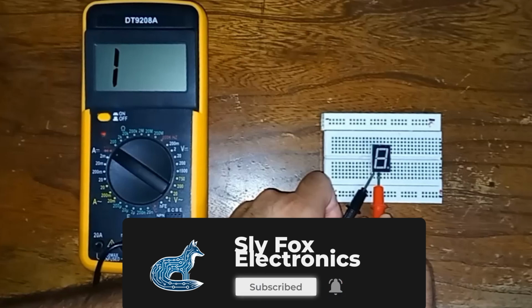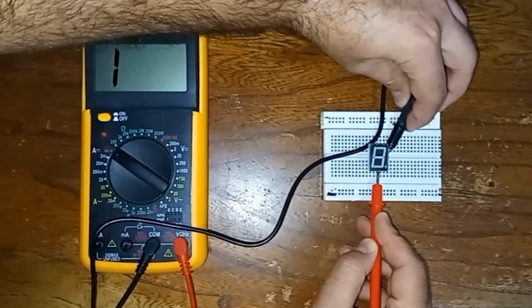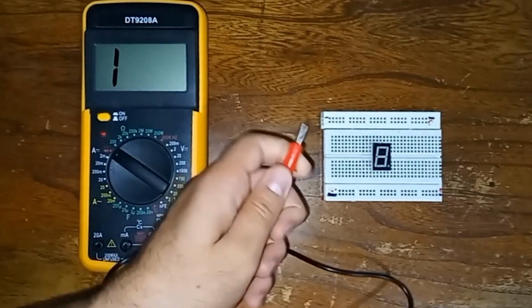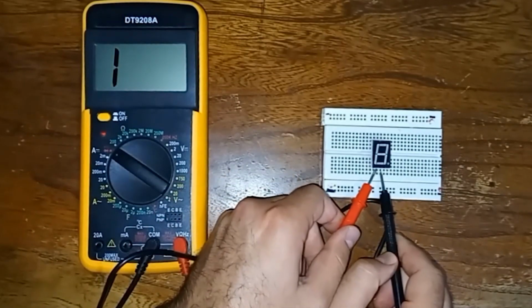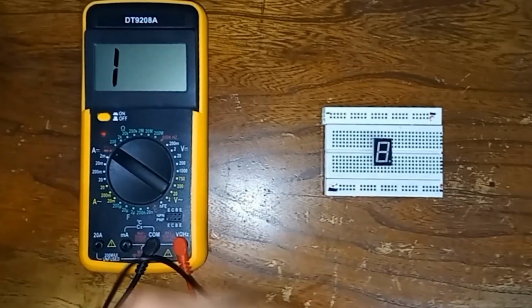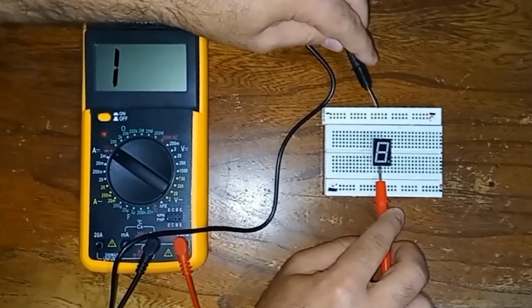It turns different LEDs on. For example, here it turned the dot on, then it turned another LED on. And you could see that it is turning different LEDs on. It means that this 7 segment is common anode.